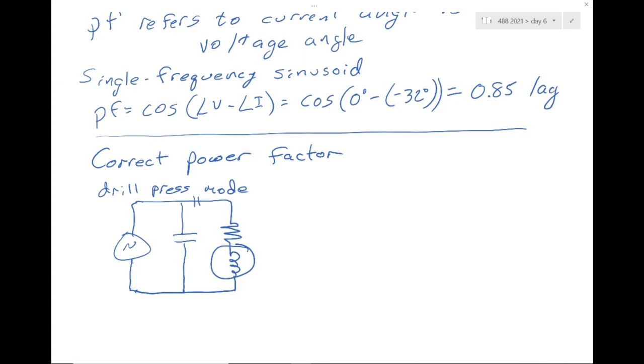It's easier to connect it in shunt. Also, if you connect it in series, it reduces the impedance of this whole thing. And if you get a short circuit, it increases short circuit currents. So that's a downside of using series capacitors. So we use shunt capacitors.